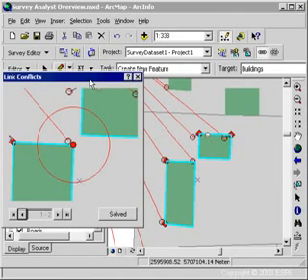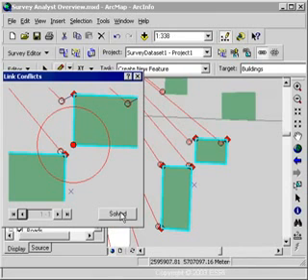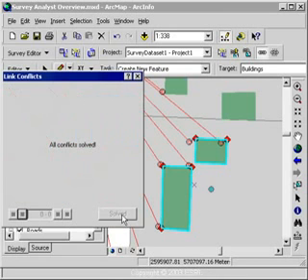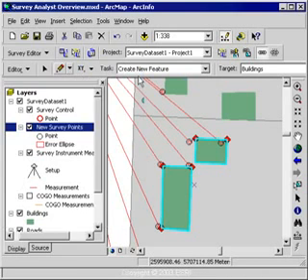In this particular case, a link conflict window comes up where I can resolve that error. I can do that interactively within the conflict window or on the screen. I'm going to solve that situation. It tells me there's one other possibility for that survey point, and that's the other corner of the building. I know that's not the case, so I'm going to resolve that link as well.